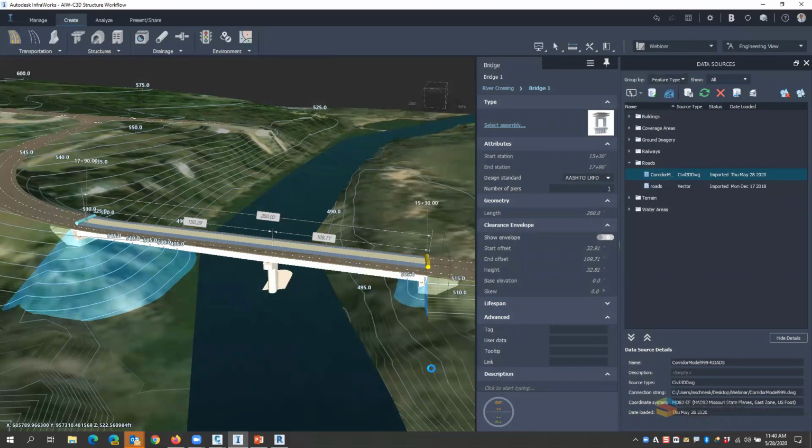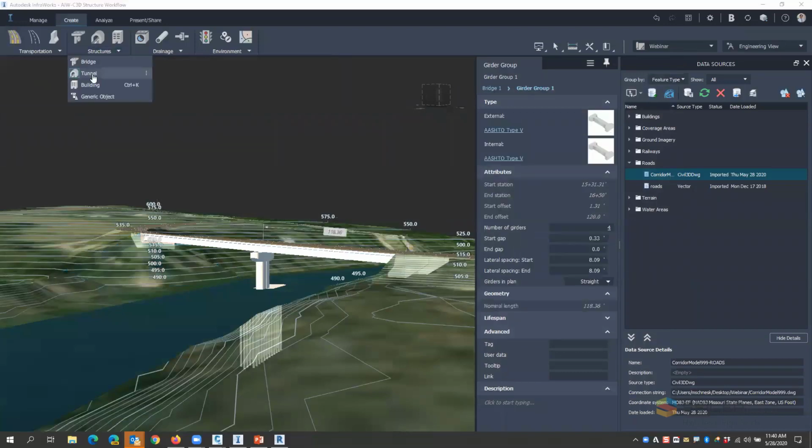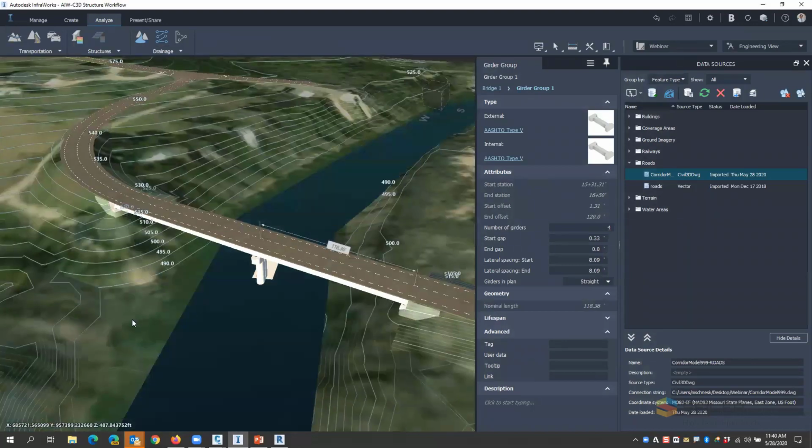So now the bridge import is going to go through, read that spreadsheet, and make any changes to this design that I want to at this point. Of course, you can do any of the structure analysis here. You could do the line girder analysis and things like that. I've talked about this in the previous webinar. If you'd like, you can check our blog there, available for watching the recorded webinars from previous sessions.